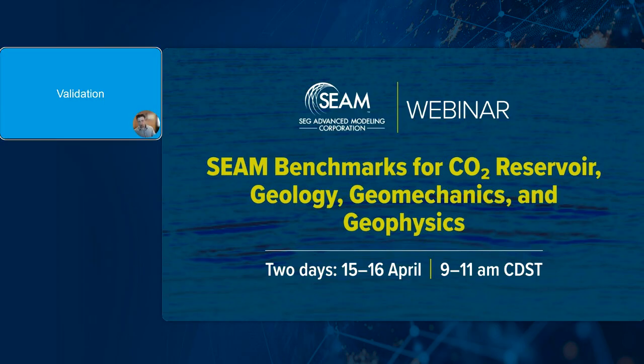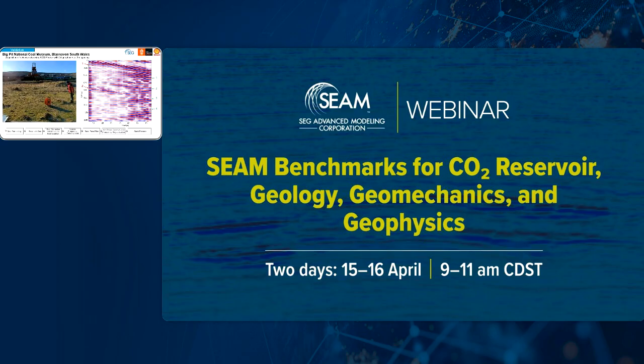Now I will briefly describe how we validated these travel paths at a reflective subvertical boundary in the near subsurface. So we acquired data at a mineshaft museum in South Wales where underground access is permitted. It was called Big Pit Colliery. Here we employed an end-on acquisition configuration with 24 geophones at 3 meter spacing. The data was pre-processed using standardized techniques to enhance the full wave field. Can I draw your attention to the repetitive negatively dipping signals in green? This is backscatter. But what type?